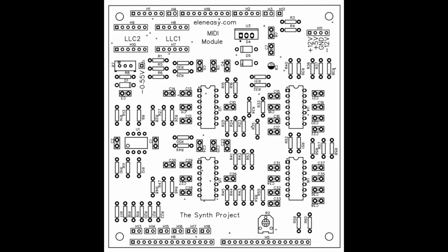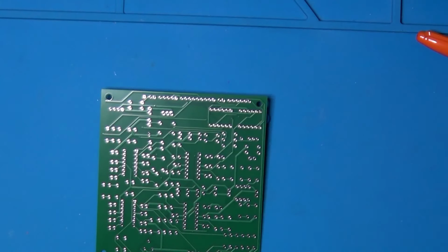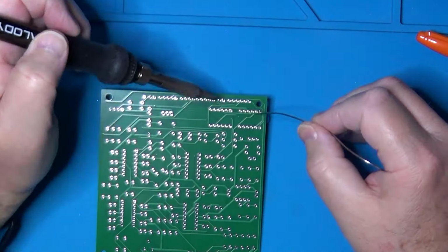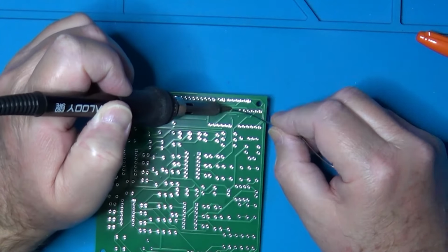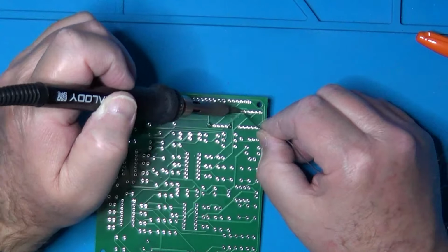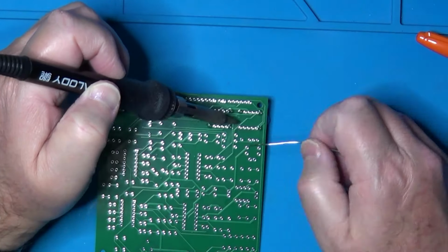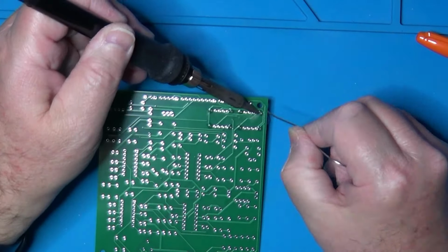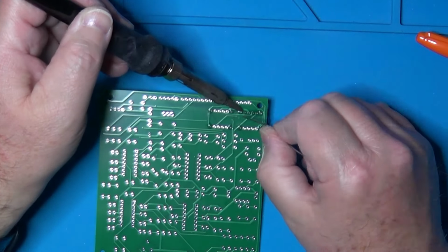That's not a real problem, because I was able to connect and solder the resistor to the push buttons board directly. Since this board needs to connect to both the Arduino and the power rails of the synth rack, I ended up mounting on it two different kinds of pin headers, the majority of them compatible with the Arduino headers, and one compatible with the connectors of the power rail.